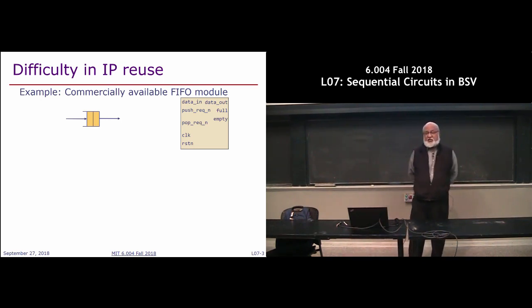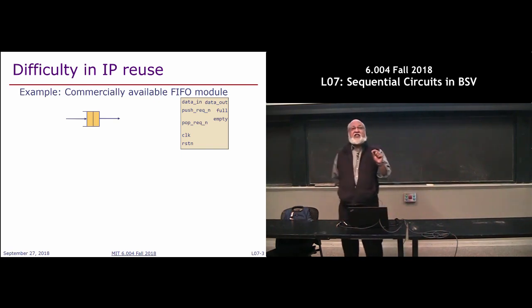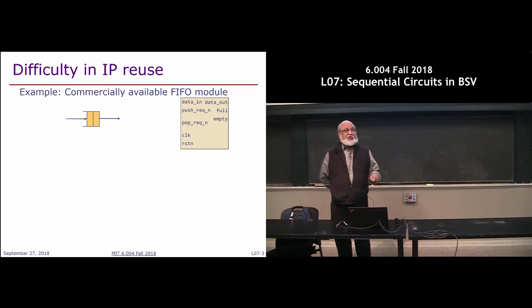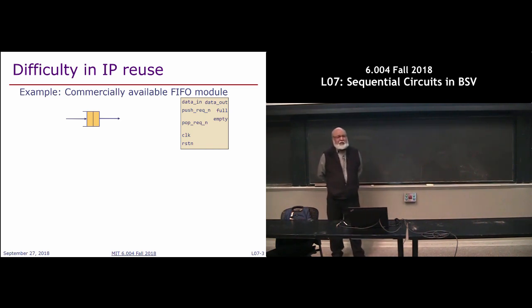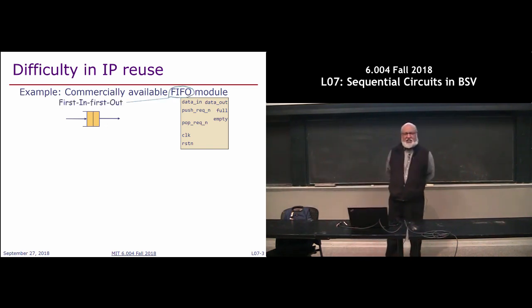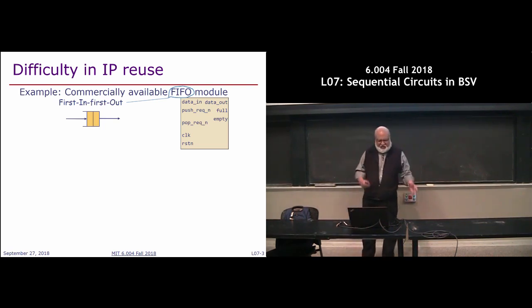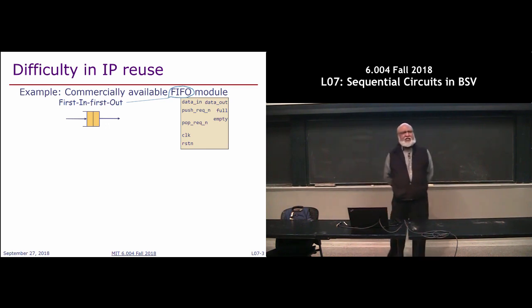So the first thing that shocked me was that this document was 23 pages. This document is not about how the FIFO is implemented. This document is about how to use the FIFO. I'm saying, whoa, I never knew FIFOs are that complicated. So here I have copied some things for you from this FIFO design. This is the block diagram that is given there, which makes sense at some level: data in, data out, push request, N, whatever N means, full, empty.